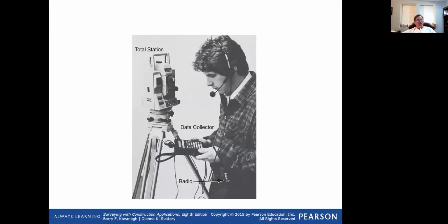This is what I wanted to bring you to. This is a total station. It measures and it shoots distances. It does both. And at the same time, this particular one has a wire going off to it, and it records everything in a data collector. My survey instrument has an onboard data collection in here. It's stored inside the machine, and then you take out a little SD card and you put that in your computer. I also have one of these, and you stick a thumb drive on the back of it, and it will transfer the information to the thumb drive.